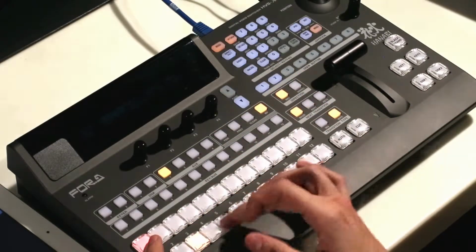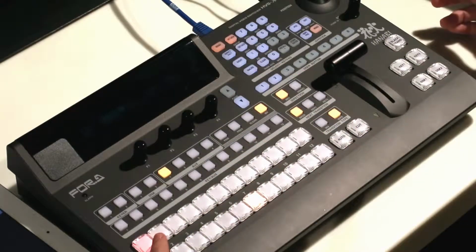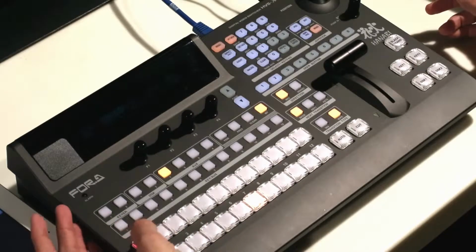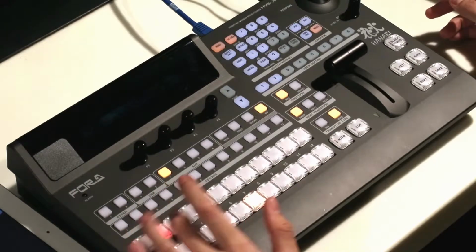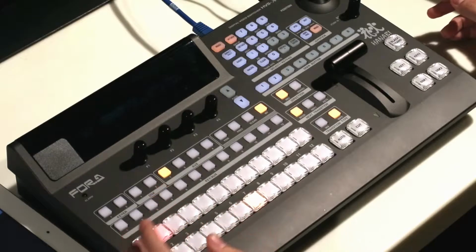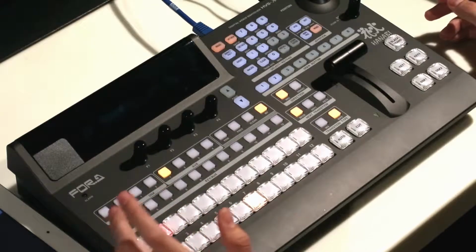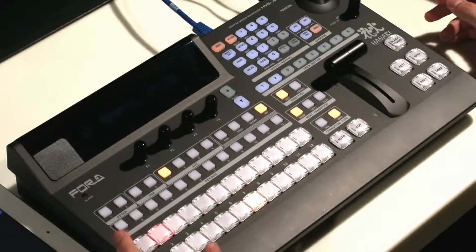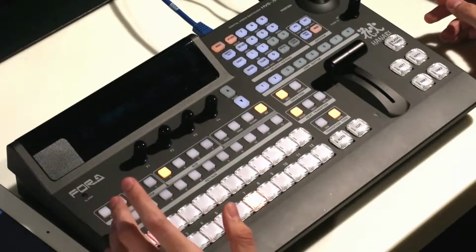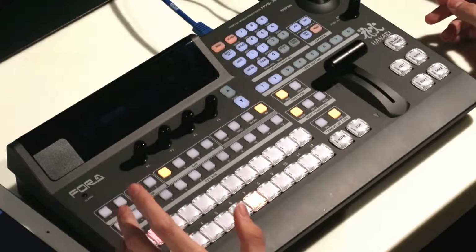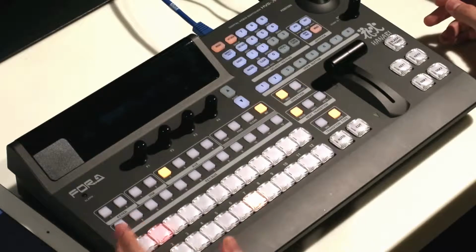Bottom bus is the preview bus or preset bus. So what you're going to take to air next. Above it you have the program bus, which is where you choose what's going to go to air. And above that you have the key and aux assign bus, which is where you assign any of the inputs to be a key signal on one of the 4 keys or any one of the auxes. It's a 1 ME switcher, so in general operation you're going to be most concerned about these 3.